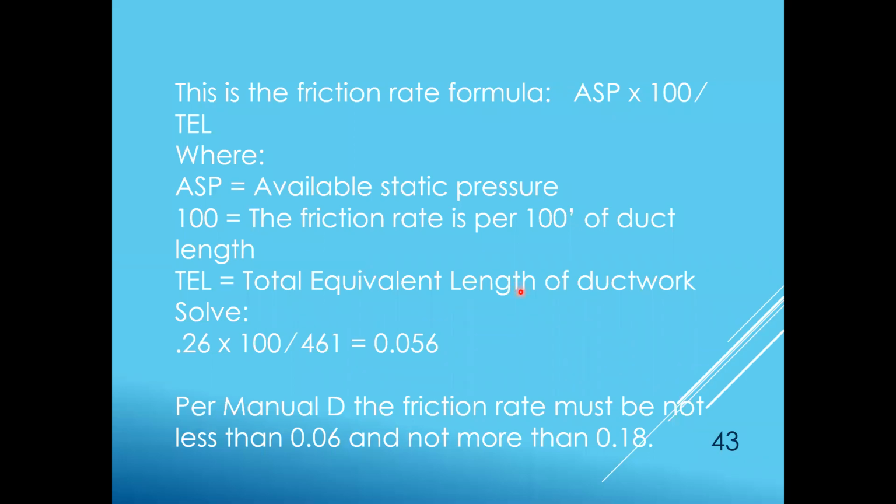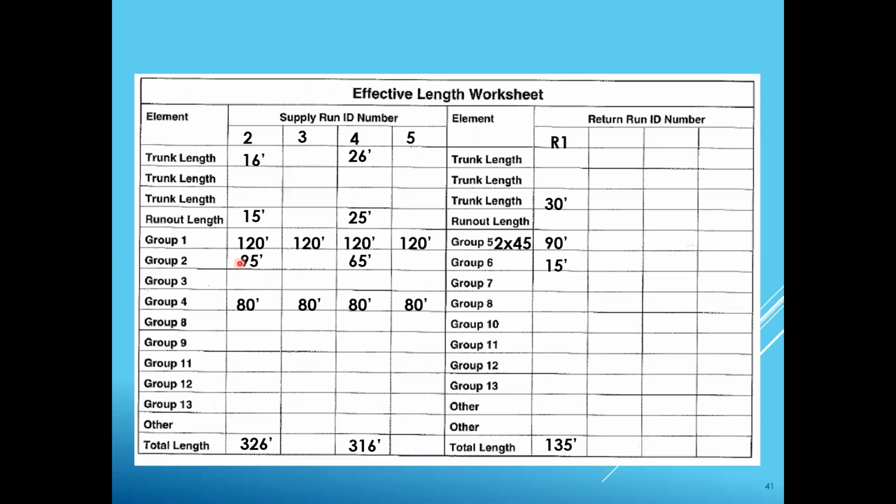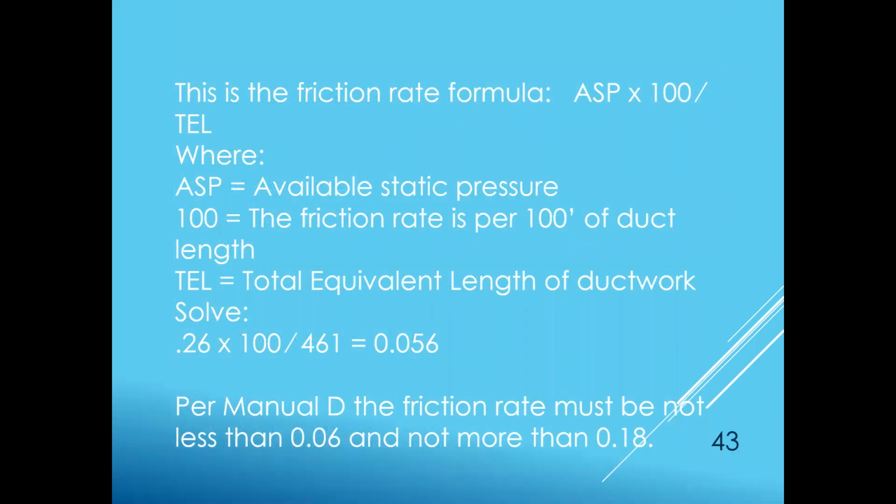And look, so in our example there, it didn't work. Didn't work at all. But guess what? They could change one fitting in this and get it to work. And that's this one right here. Remember that one fitting? If they use a decent fitting off the top of the furnace, they change one fitting in that entire system, it works wonderfully. Because I just went from 120 to 20. Took 100 linear feet off of it. Right? So yeah. That's the nice thing, is that even on paper, they can figure out we're in bad shape and change one fitting and we move on with life.